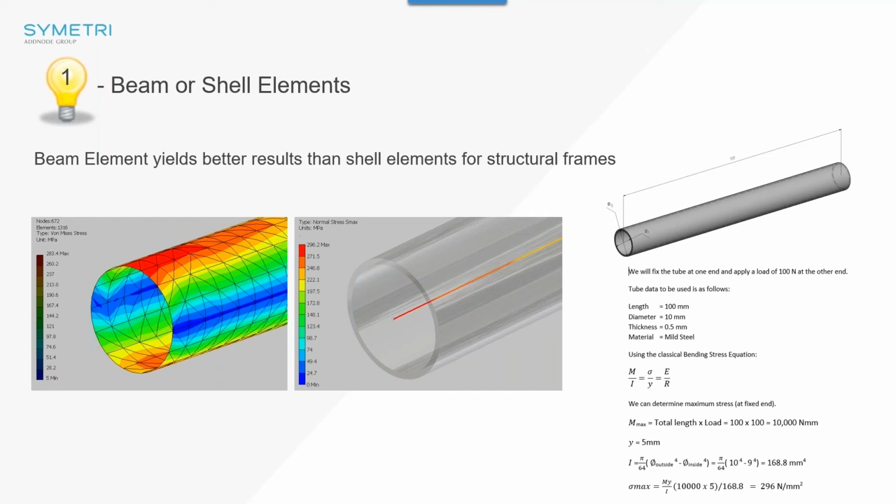So when you are doing frameworks, I would suggest to customers and clients to consider using beam analysis as well, because the software works absolutely amazingly, and beam elements are absolutely accurate. And one more tip, when you're doing beam elements, there is no need to change the mesh 3 times, 4 times. You just refine the mesh and run it, and you have a solution.